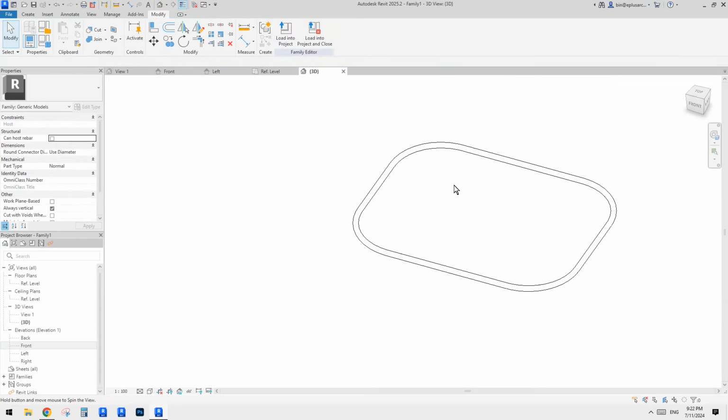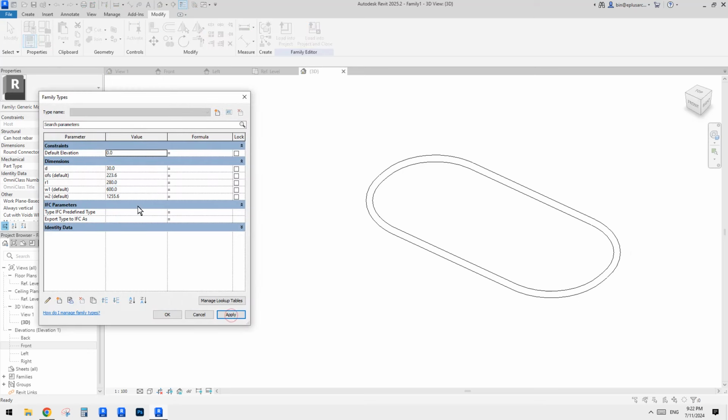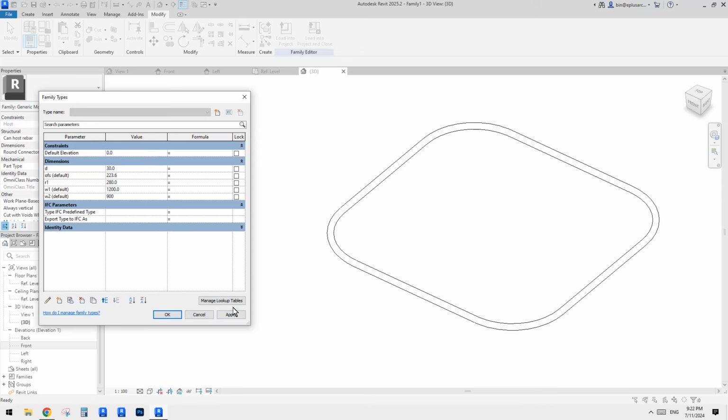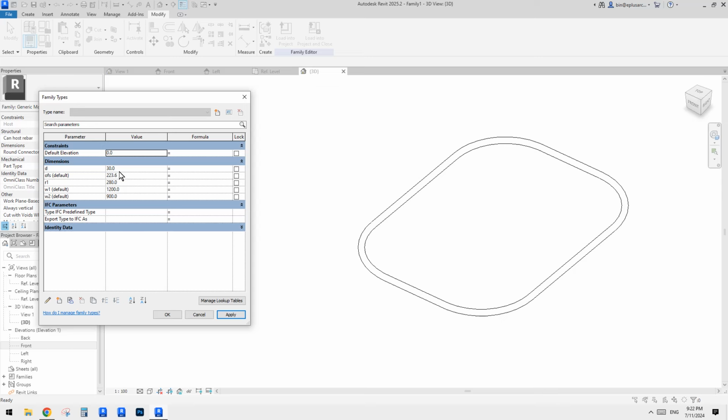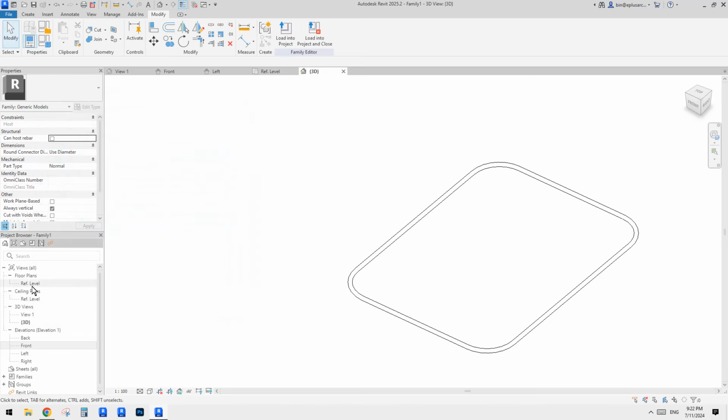So this is this, and then we can adjust the size. For example, I'll change to 600, 1200, 900, something like that. And then also the radius. The D can reduce the size. Offset is the distance from the ceiling, so we'll see it will go down. Radius is this radius, so if I type 150, right? So now go back to the floor plan.